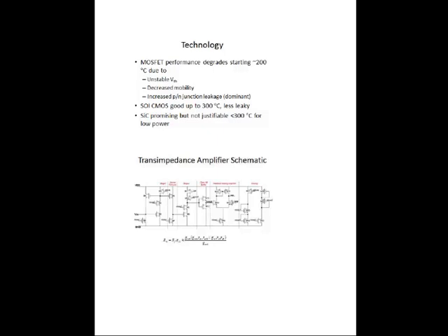It has about 100 kilo ohm resistance at room temperature at a typical corner. The swing over here is about 10 millivolts, so its linearity is acceptable. And the maximum current that you can apply is about 100 nanoamps. The second stage is a source follower, basically to level shift the output for the second stage voltage gain, which is a cascoded amplifier.